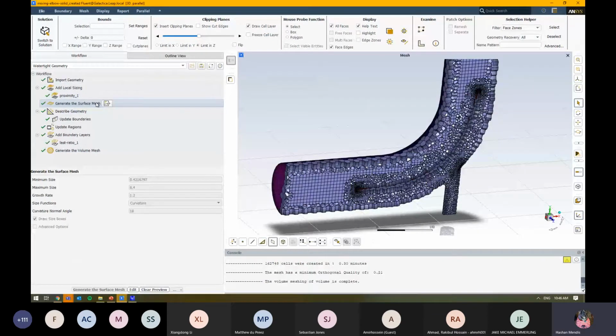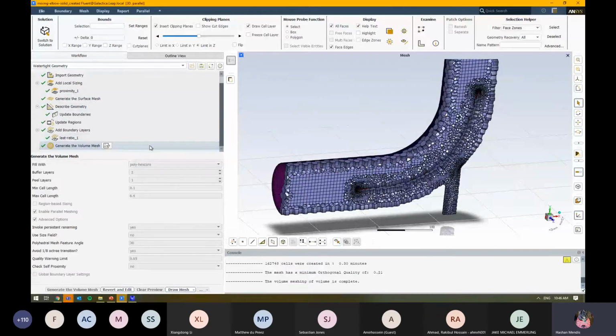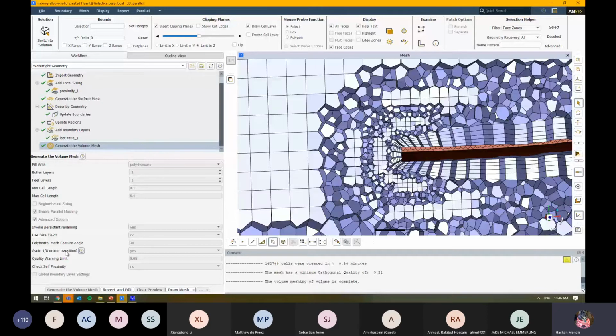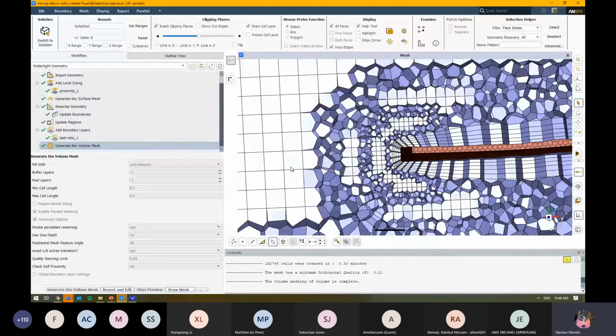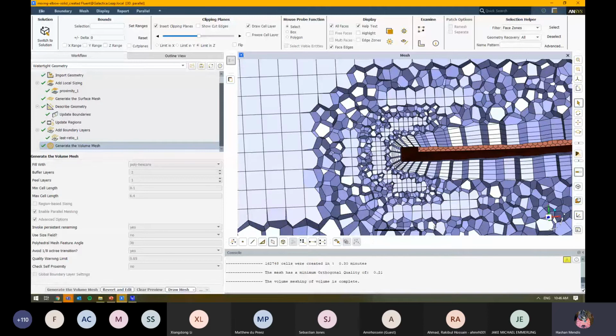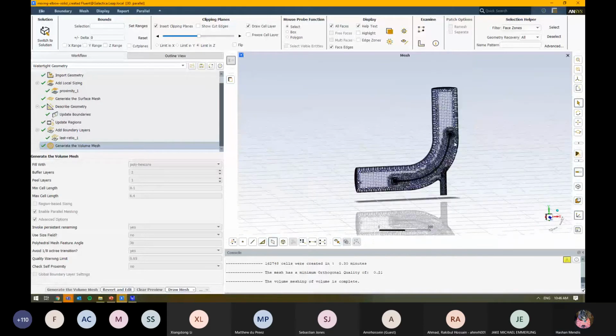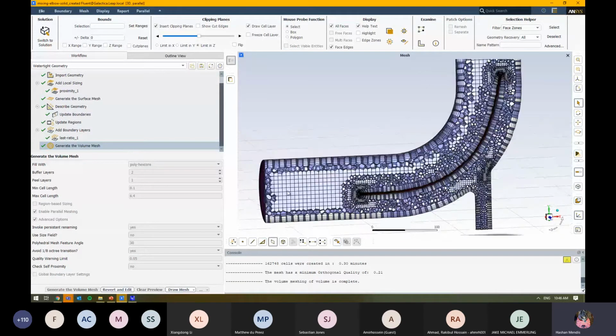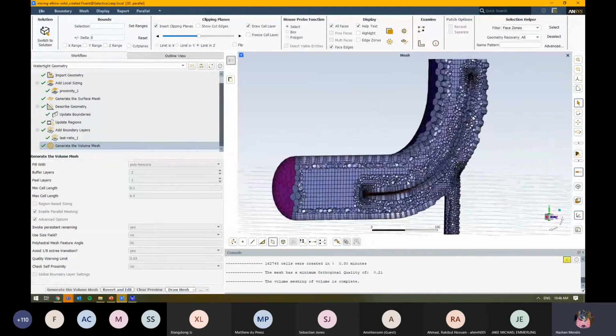Always try to make the surface mesh the best that you can, right? So I should try and get a surface mesh of around 0.5, and then that will make making a good quality volume mesh a lot easier as well. So you'll notice again, it's around here, now that we've got this avoid 1 to 8 octree transition, instead of this large jump from one to the other, we've got a couple of poly elements in there transitioning through there, right? So for internal flows, generally, depending on what you're after, this is something that you can do as well.